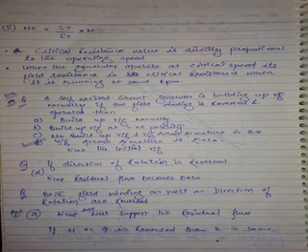Plot OCC at 900 RPM. What is 900? Critical speed. Now you want the critical resistance of this machine. What will you do? You will plot a tangent. I am repeating here again. You are plotting OCC at 900 RPM. Let 900 RPM be NC. I am asking you, what is the critical resistance of this machine when it is operating at 900 RPM? You will plot a tangent and you will get a point.